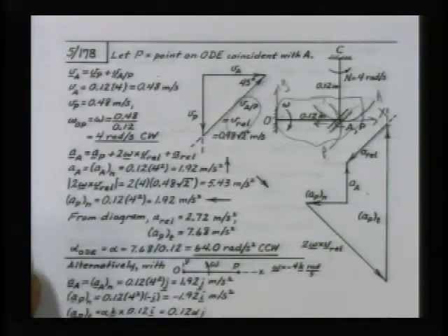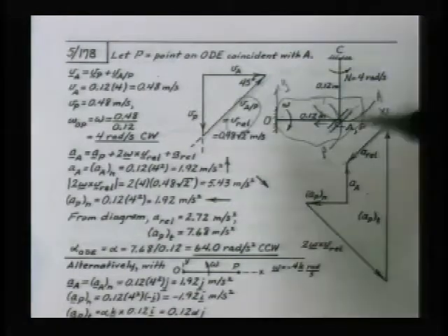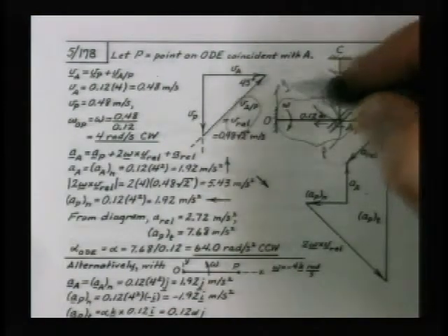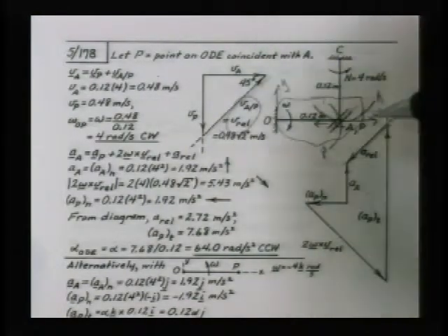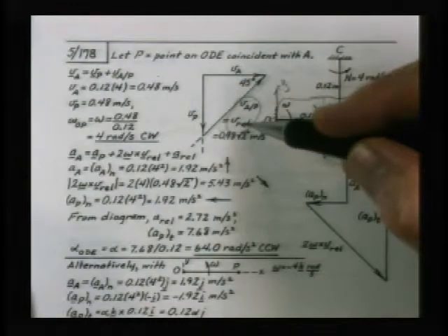Did you say that their coordinate axis that they chose is fixed with relation to the plate, and that it would rotate with the plate? That's correct. Well, then wouldn't the coincident point in the slot on the plate have zero velocity, zero acceleration, and all that? The point P, which is locked on that plate. Correct. Yes, but A moves relative to P, and that's what the V rel and A rel terms are.